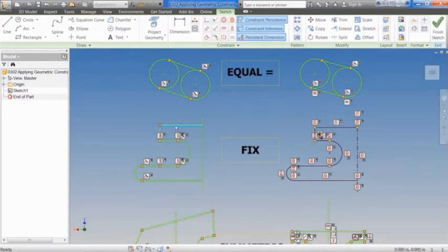If you have a very complex shape and you're doing a lot with it, with a lot of constraints in here, a lot of control, but let's say I'm doing something else and I need to dimension to it. If I was to try to dimension to this shape, say to that there, put a dimension on it, it actually moves my geometry up to that secondary shape. Well, what if I'm still working on this, but I need to lock it down for something? If I undo this back, what I can do is select it and hit the little padlock here.